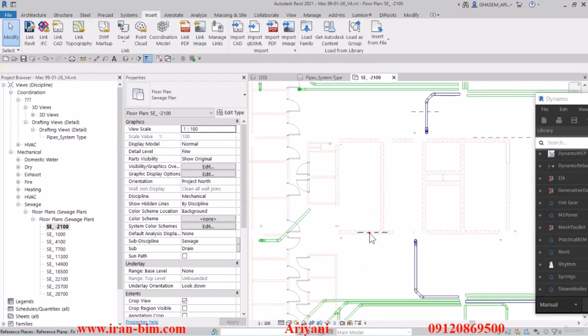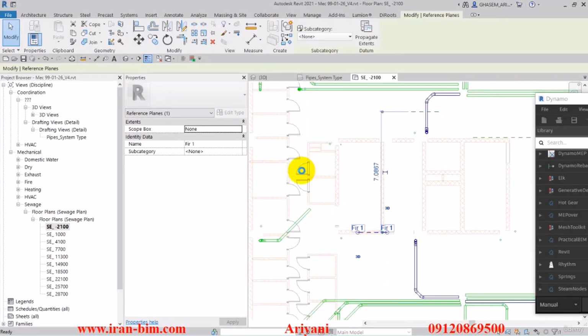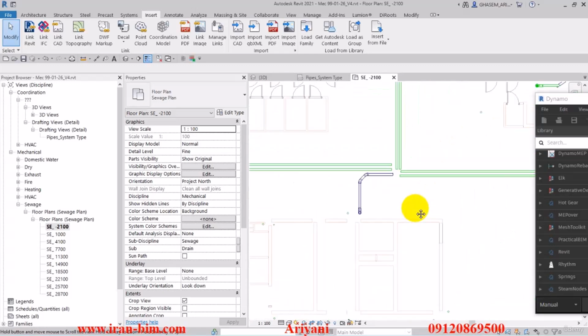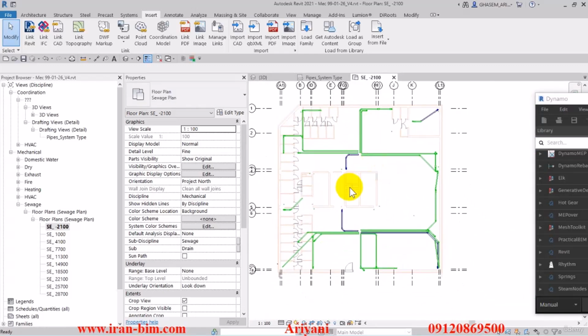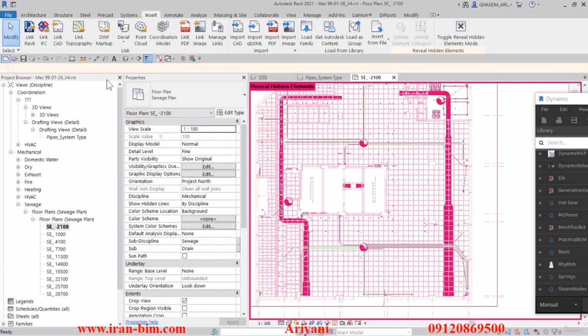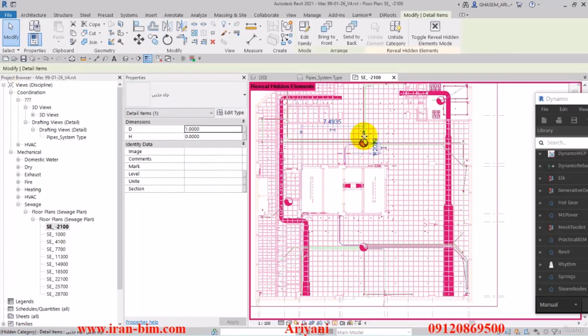And the reason that the doors aren't fixed here yet is because the doors themselves have a subgroup which we've already talked about in the architecture. And the show panel, those are the subgroups of the door. Let me see which one of these items we didn't need to hide, but we've hidden them, and check that quickly. So I'll select the walls that we have here and then press the unhide category option to show them. All right, then press toggle reveal hidden elements mode.